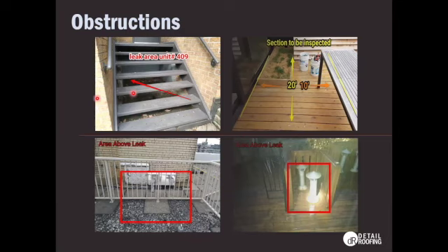In cases like this, we might have another contractor recommended to remove some of the fencing that's in here, the planter that's built in, or have these railings removed so that we can fully investigate everything that's going on. Especially in this case with the paving stones, these ones that aren't bolted in, we could lift those and investigate what's happening. However, we're not going to see the full scope of information and everything that's happening in that area.